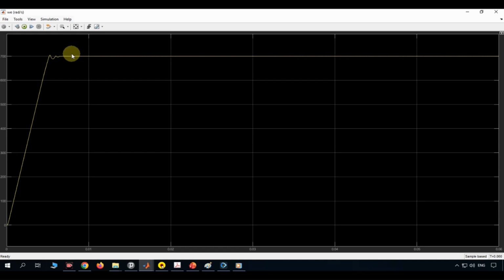At 0.04 seconds, when the load steps down, you might expect the speed to jump, since the motor is suddenly producing more torque than the load requires. But the speed trace stays remarkably flat. The disturbance is barely visible. The PI controller reacts so quickly that the speed never deviates significantly. That's exactly the behavior you want in a high-performance servo drive.